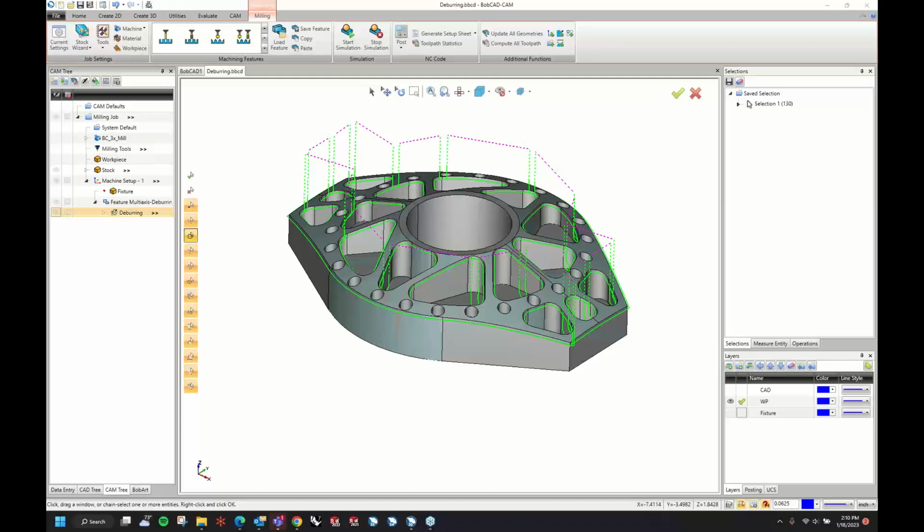So if you want to save a crib for a particular job, you can throw that on a network drive and any computer can grab that and load it for a job that they might need it. Really, that's the way to use it. The tool library is unique to each computer, but you can have a master library that you add tools to, you save that library somewhere, and then people back it up. But that's really the only way you could do it.